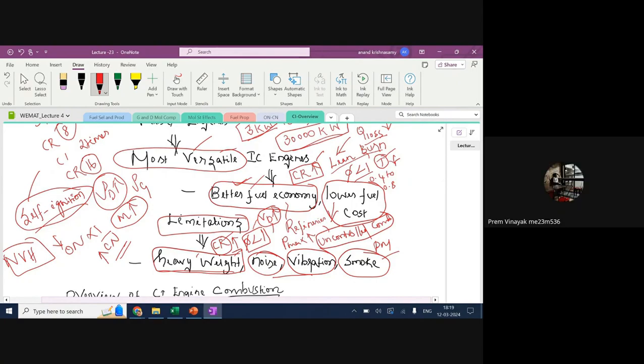This smoke or particulate emission is again a problem in a diesel vehicle. In an SI engine, you don't have smoke. In the second module, we are going to discuss the pollutants, the regulated pollutants. SI engines don't have this particulate emission. Why? Because of lesser fuel density, sir? Homogeneous mixture, less carbon molecules, sir? Homogeneous mixture is the primary reason.